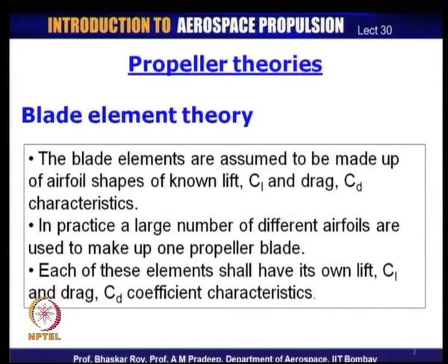There are of course, various versions of the blade element theory. We will be doing the elementary version. There are more advanced versions of blade element theory, which are beyond the scope of this course, and we shall not be doing them. But the fundamental blade element theory that we will be doing provides a sufficient backdrop for understanding how the propeller blades are designed, how the propeller blades finally go on to create thrust, and how the aerofoil shapes with characteristic values of CL and CD actually help in creation of thrust.